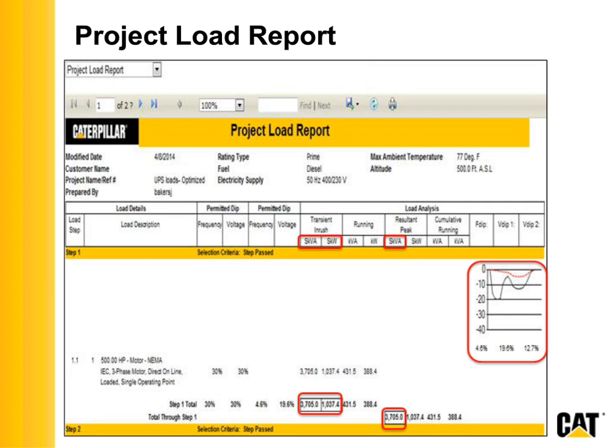And so what we do is we box the values that are highest, so you know right which step to go to on your add loads page, which step to work with to reduce any sizing parameter, whether it be your starting kW for your engine, your running kW for your engine, your running kVA and starting kVA for your alternator.